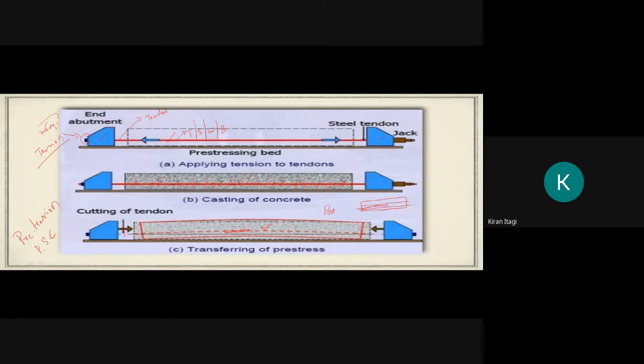It is not a pipe, it is called a duct. So the tendon is not touching, or not coming in interface with, the concrete. Keep that in mind. And here there will be a frictional bond between the wire and the concrete. That is the most important thing.